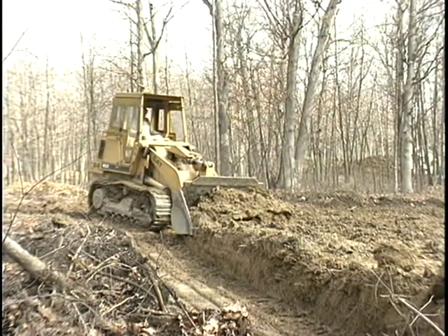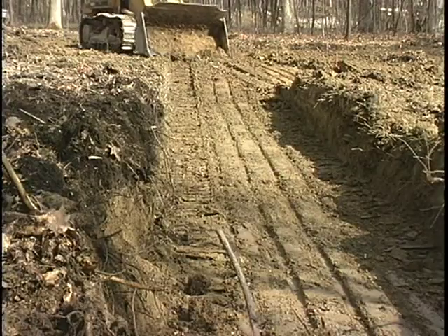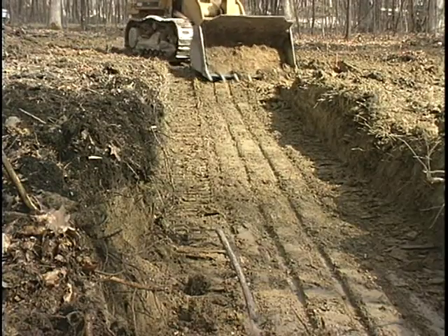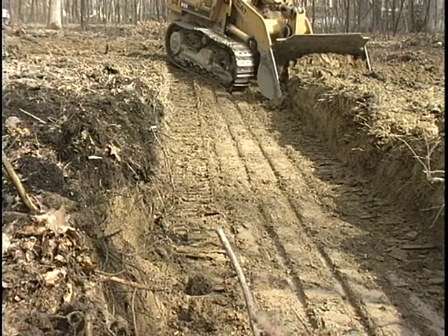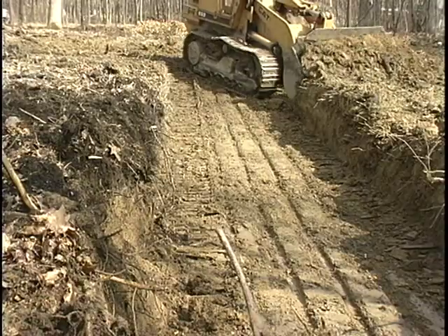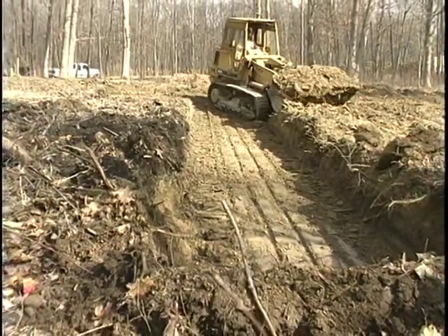When excavation begins, heavy equipment operators dig the foundation hole next to surveyor stakes. Since the stakes are located several feet from the exact build site, the excavation will be slightly larger than the foundation, so workers have room in the hole for erecting the footings and foundation walls.